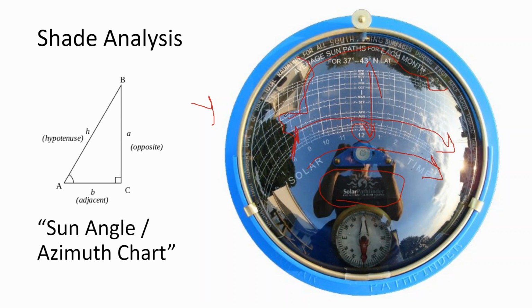Actually, this house here is not really a big issue, because by the time it starts shading my array, that's going to be 9 a.m. in the winter half of the year, and the days are already going to be shorter. I'm not going to get much sunlight on the array until 9 anyway. PVWatts doesn't show my solar array turning on until 9, so I don't have to worry in the wintertime about stuff before that. Really, maybe it's this tree right here that could be turning off my solar array at 2:15 that I need to be worried about.